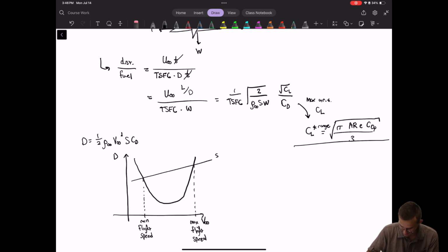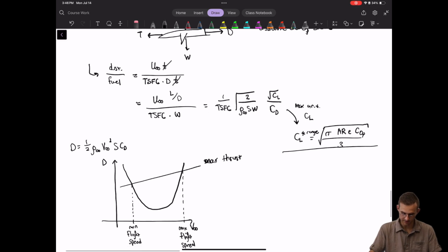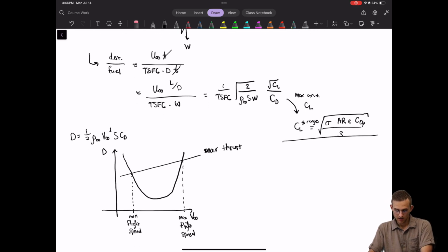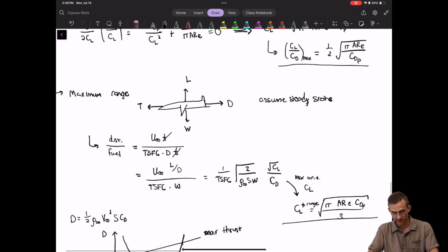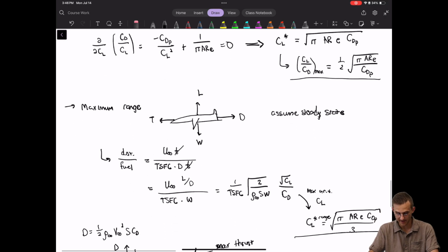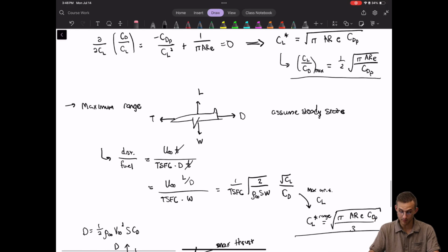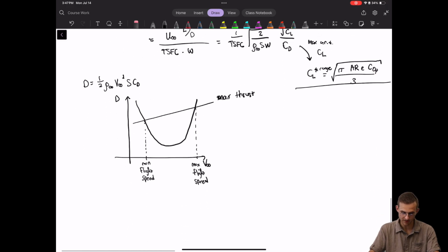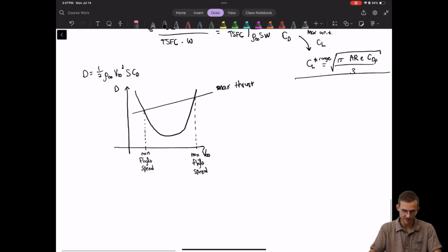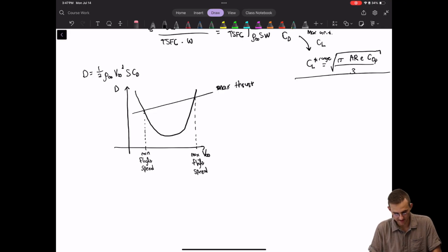So this thing is our max thrust. Okay, so within that frontier, we can choose our design, making certain trade-offs, like how do we want the ratio of lift to drag to be? Do we want to optimize for that, or do we want to optimize for our maximum amount of range? And interestingly, we don't get the same answer in both cases, depending on what we're optimizing for. But this maximum thrust plot here shows you what our range of flight speeds is limited to being,